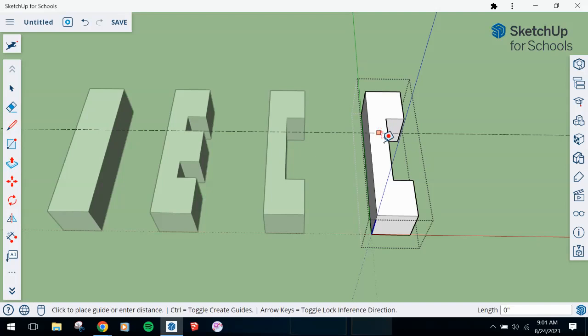And from this line, then you're going to come down a little bit. You're going to come down 3/4. That's 3/4 of an inch. And just to confirm, I'm going to measure from this line down to here. I'm not going to click again. I just want to see the number show up on my screen, 1 1/8, and that's what I'm looking for. So to get out of that, I will press escape, which is in the top left corner of your keyboard.